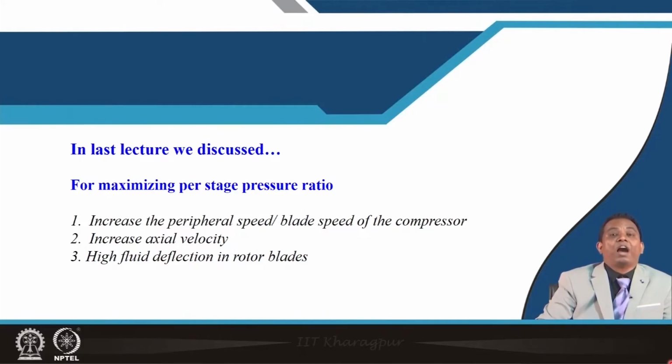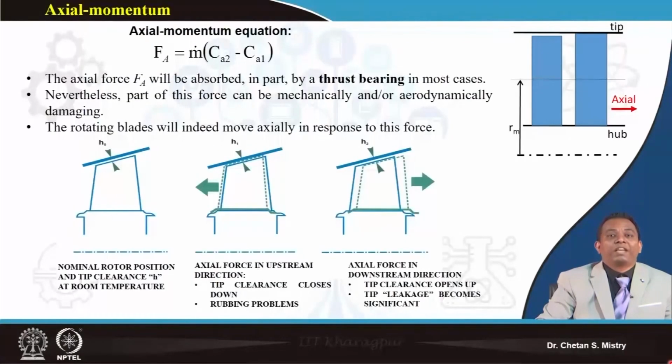Now when we have a higher deflection angle for the rotor and we are looking for axial exit, the design for the stator also becomes very challenging. That is the reason people are finding different ways to address these issues. As we move ahead, we will discuss the development activities going on globally to address these issues. Now let's move to the next case.